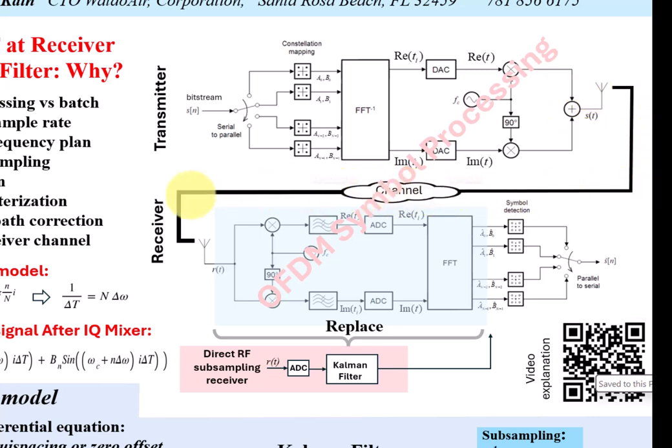After transmission through the wireless channel, the receiver's IQ mixer separates the signal back into real and imaginary components, then low-pass filters both I and Q channels to remove the 2x carrier parasitic noise. The receiver's two baseband channels are digitized with separate ADCs and input to the FFT. The FFT output is the AB coefficients that contain the QAM data.